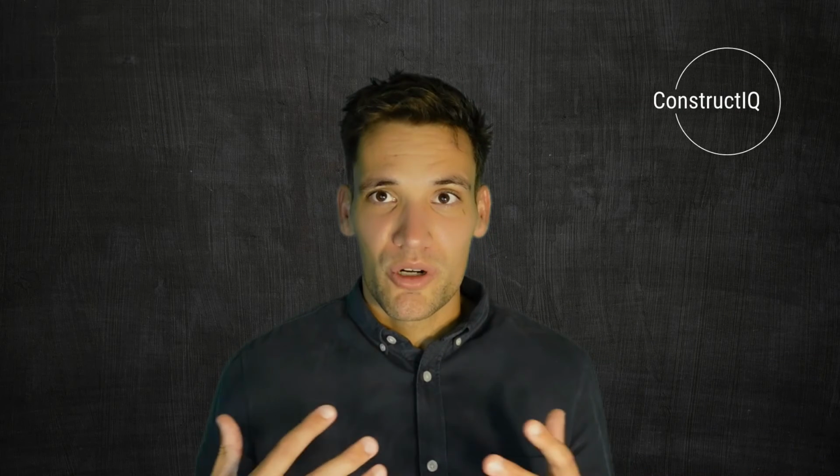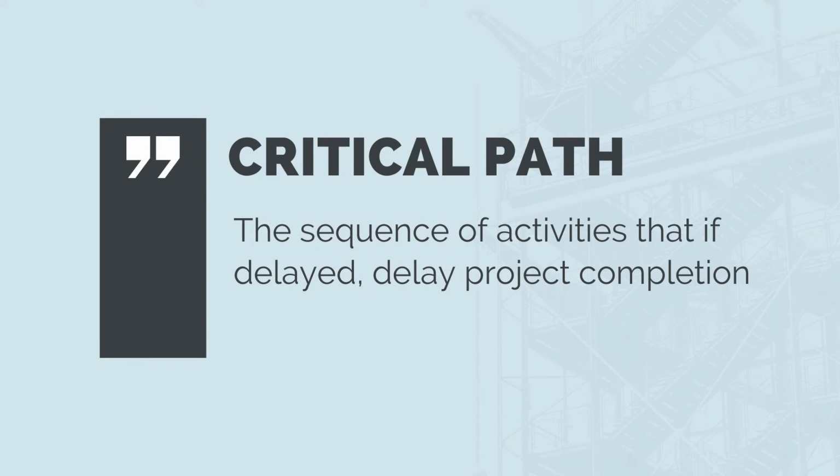A really important concept we need to understand is the project critical path. Now, the critical path is probably one of the most confused terms in construction. At its most basic, a critical path is the sequence of activities that, if delayed, delay project completion.